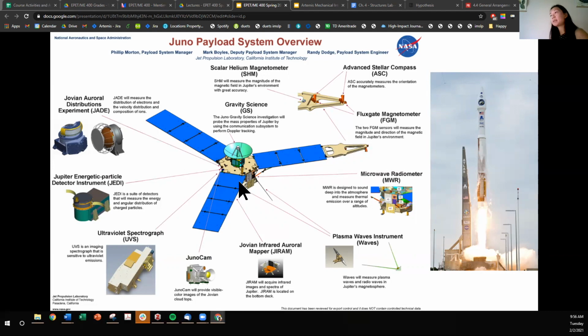It had to be in some stowed configuration, and then the solar panels and other, like maybe the antenna dish, could then be deployed. So yeah, it would be up to the structure's subsystem to figure out how the collapsed version of the spacecraft and the deployed version of the spacecraft works, and how to transition between those 2 configurations.